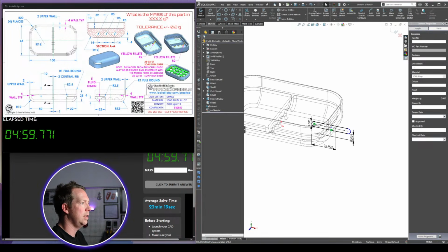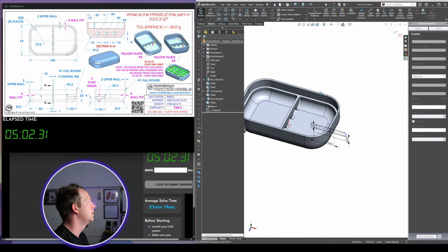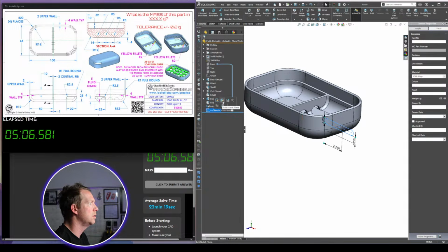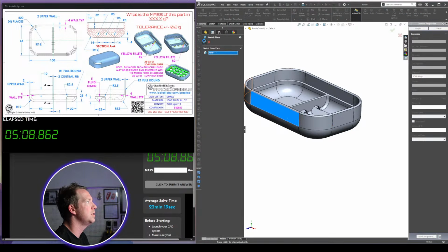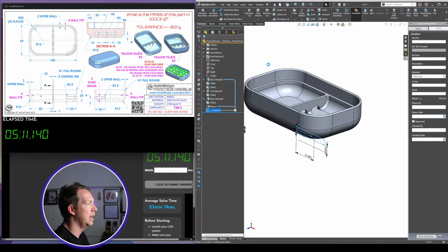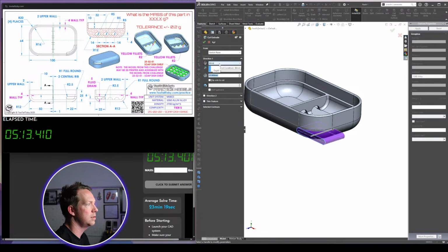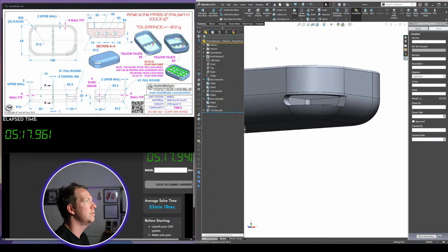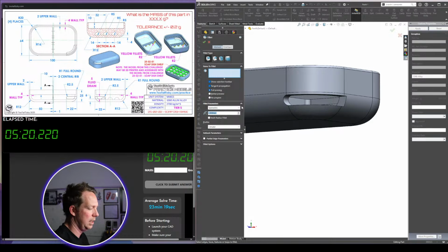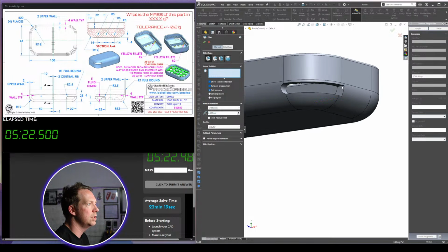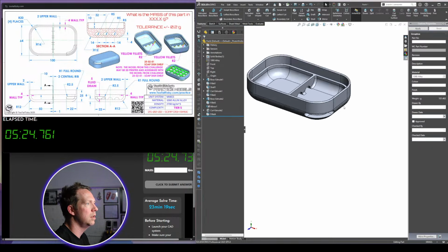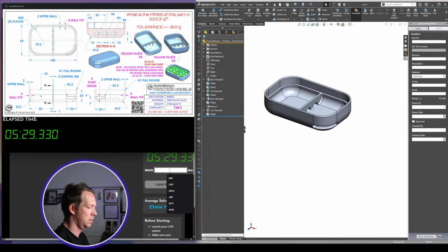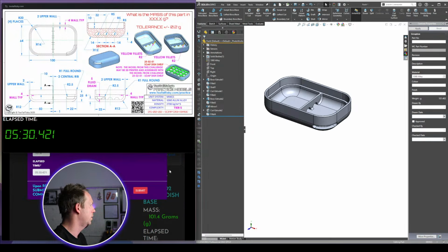Alright, so that's fine, it can be underdefined. How deep does it cut? It cuts 22. So what I'm actually going to do is just change the sketch plane, put it on this edge. Then I'm going to cut it 22 millimeters that way. And then all I need to do here is a full round fillet or a 2.5 millimeter fillet on these edges, and this should be it. So 101.4 should be the answer. There we go.